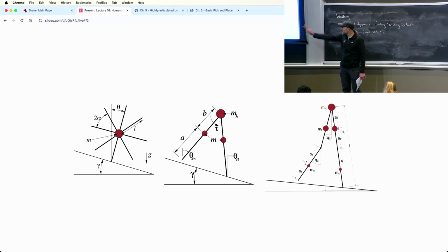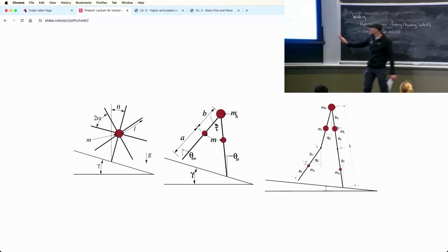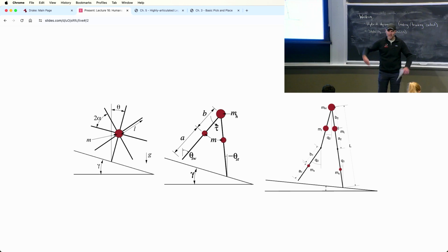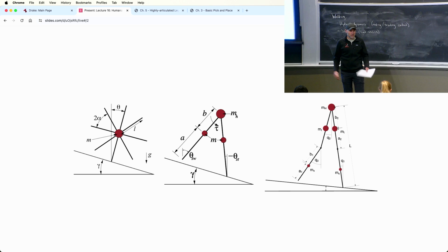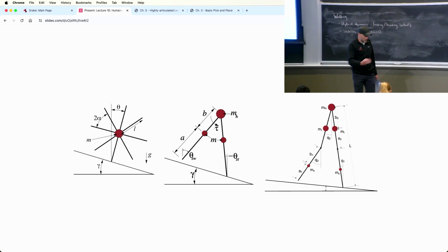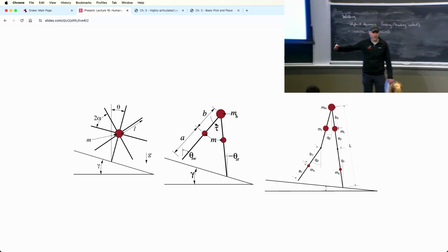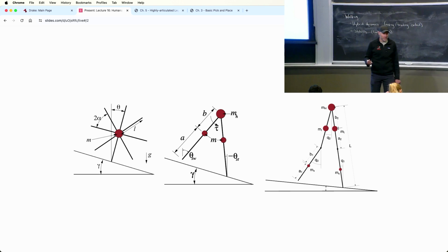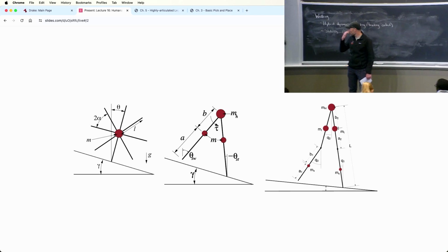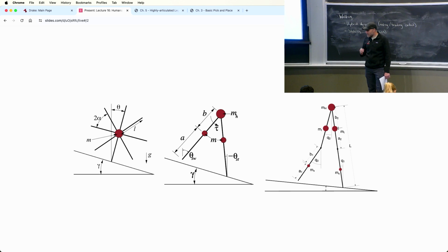But as we keep going sort of to the right here, it seems like we can just add more and more degrees of freedom. Suddenly we get foot, upper body, torso, all these things, right? We're just adding more and more complexity. And although the math works, the solver is going to have more and more trouble, I think. It gets harder and harder. These are tractable. We're seeing people solve them. Boston Dynamics is solving them at a very high rate for seemingly the whole set of equations, okay? But it does feel like the problem's just getting arbitrarily harder, which is a little bit at odds with the fact that humanoids have been walking well for a long time.